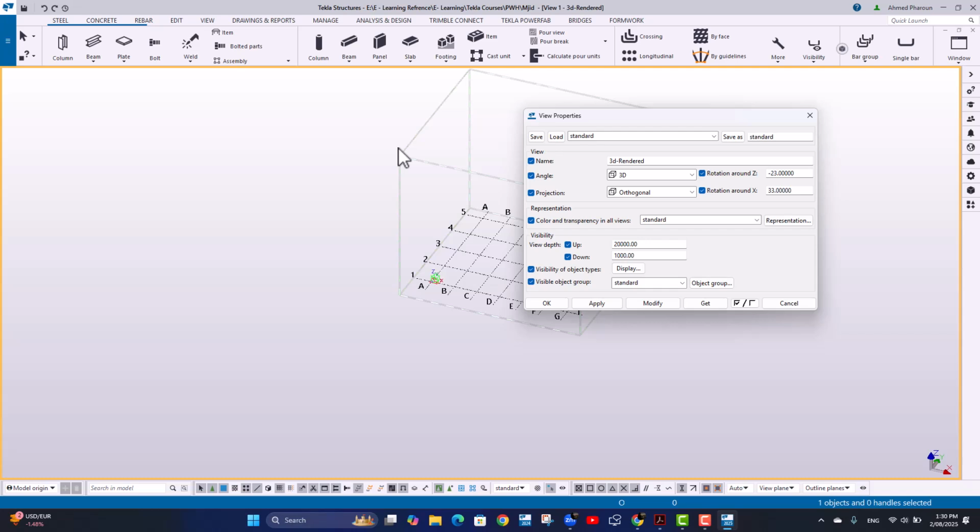You can modify its length, its color, its profile, its everything. You can modify its characteristics without affecting the attributes. At the same time, if you update the setting for the attributes, it will never affect the member or the object that you have created inside Tekla. So it's very important to know that saving and loading attributes is a helping tool to set up quickly the members you currently have to do, but not affecting anything right now or in the future.